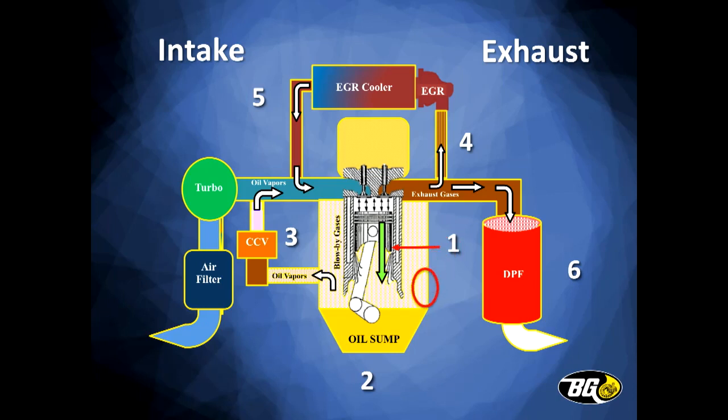That's number 2. So now I've got elevated sump pressures. Those elevated sump pressures have to be vented. On a gasoline engine, we use PCV systems, positive crankcase ventilation. Diesels, until recently, within the last decade, used to vent these through downdraft tubes, if you would imagine in your mind's eye, rather than having a PCV system recirculating it back to the intake.